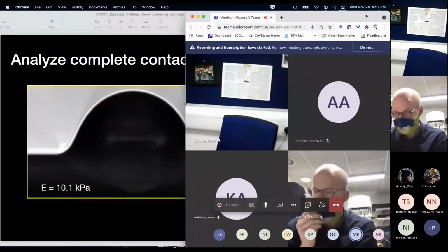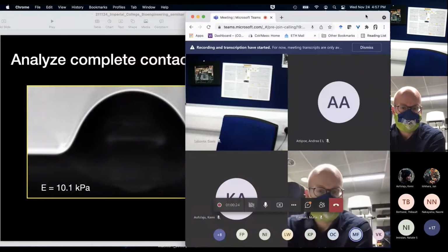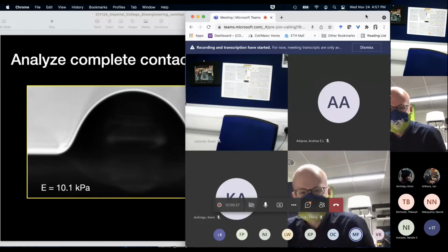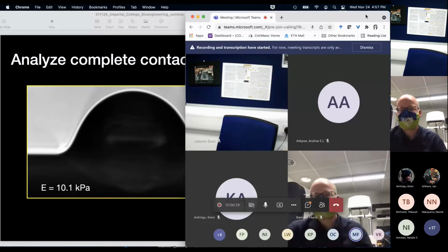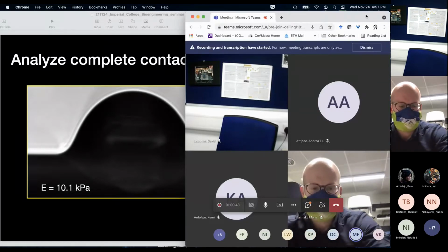And actually where that wetting limit comes from is also a super interesting question. I took it out of this talk because I didn't quite have enough time to say anything about it. But we have actually done the experiment of doing a salinization of the surface, to modify the surface energy to be less wetting to the silicone, and indeed it cuts it off earlier.